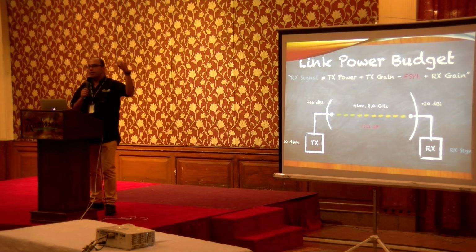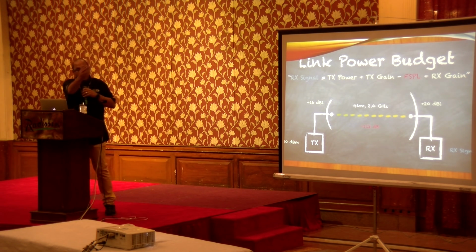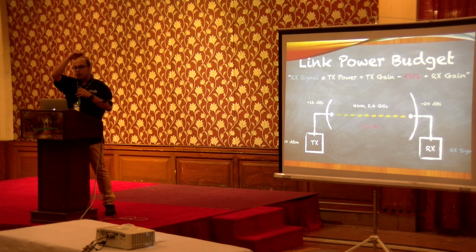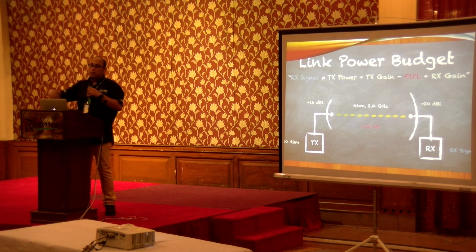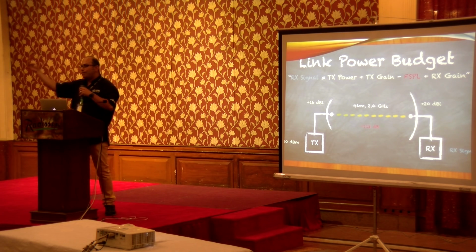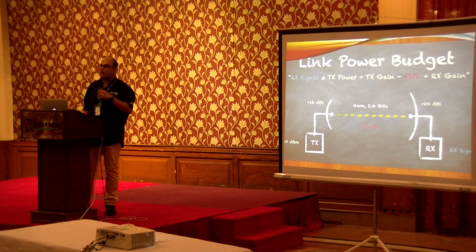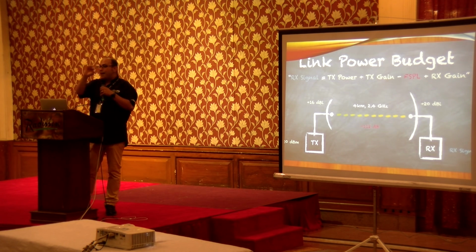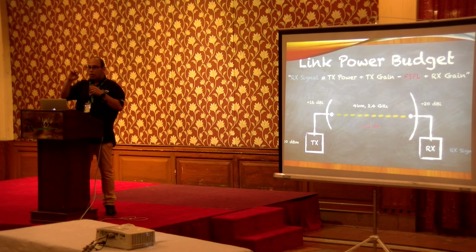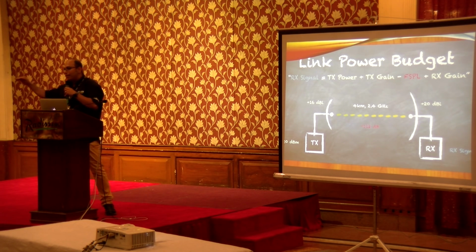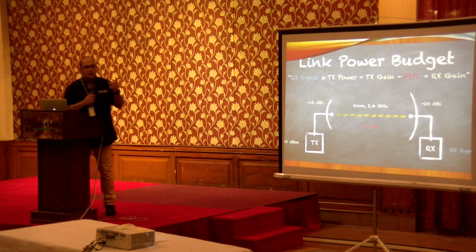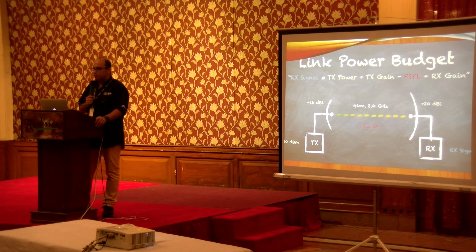Now your signal is on the air. We will talk about modulation, we will talk about other things, but the data is on the way right now. Because of noise, because of rainfall, because of obstacle, because of any problems, any reason, the amount of signal, the amount of power will be lost by traveling the distance. Even if there is no obstacle, there is no noise, there is a concept, we call it free space path loss, FSPL.